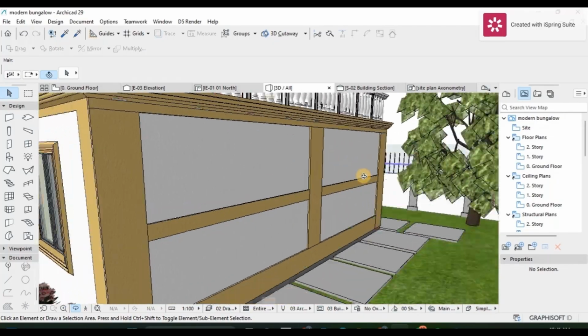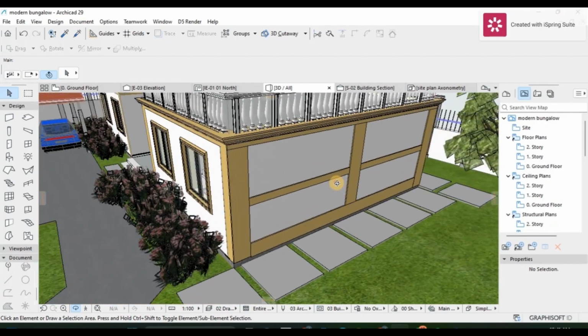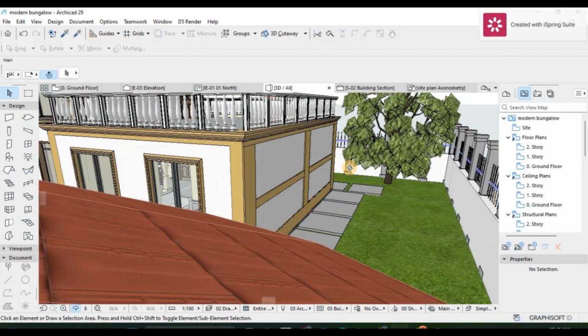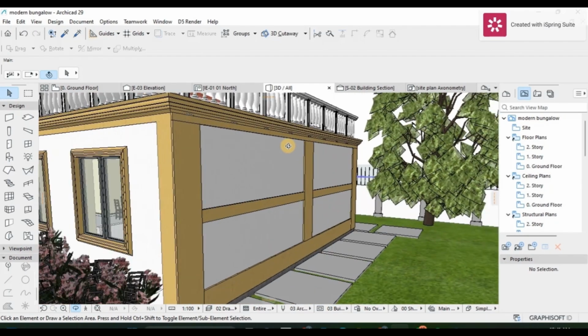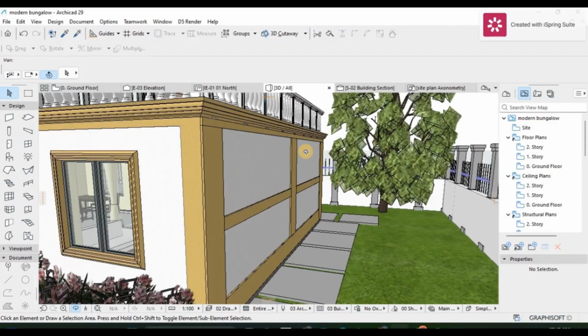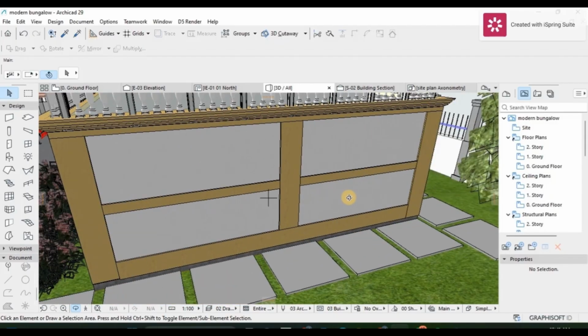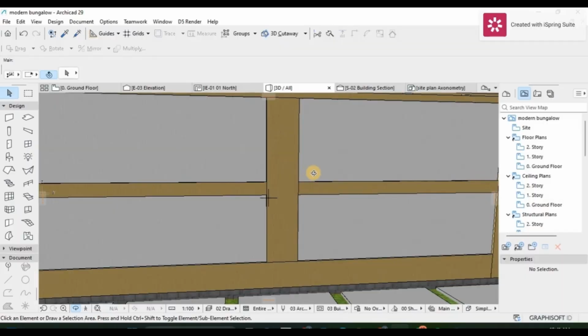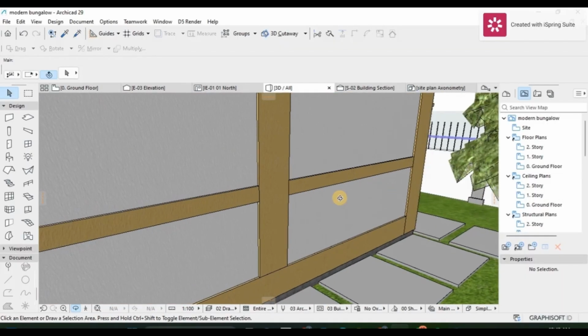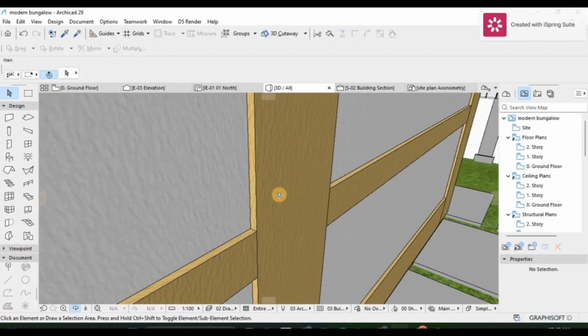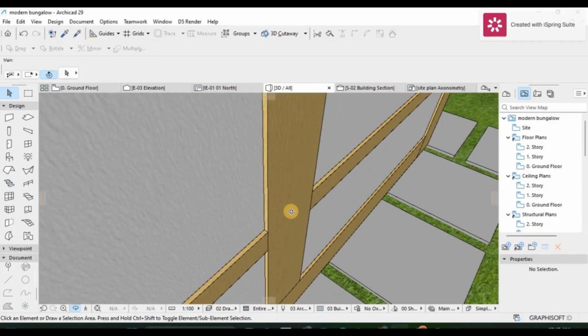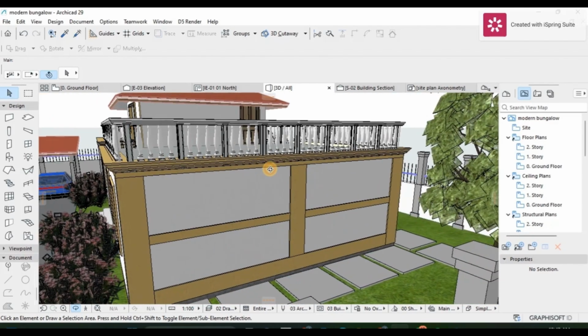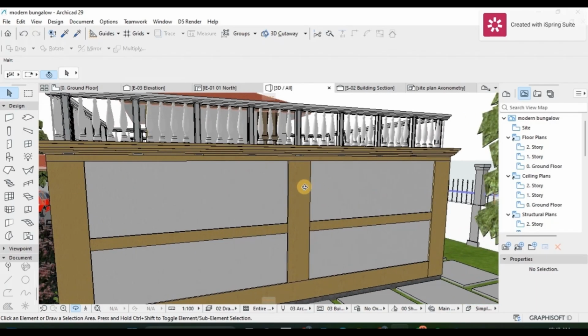It's just a simple thing, but you can use it in your design to achieve many things. You can use it to achieve maybe a pattern on the walls or in the interior. So that's how you can assign different colors onto the same wall, and not only different colors, you can also assign different thickness onto the surface finish of your wall. So yeah, just by using the Morph tool and drawing out your different patterns.